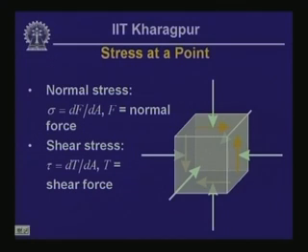So, you should notice here that all the 4 shear stresses will act together. In order to maintain equilibrium, all of them have to arise together, or they are not going to arise at all. So, the magnitudes of each of these 4 shear stresses shown on this particular element is going to be the same. Okay. Similarly, we are going to have 4 more shear stresses.